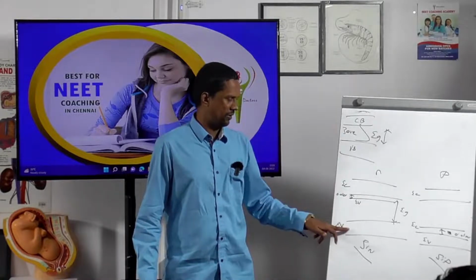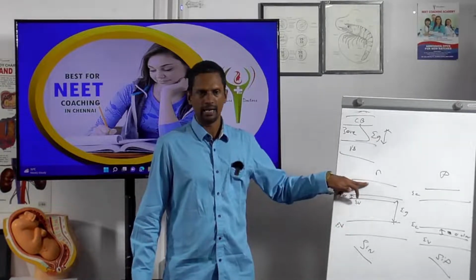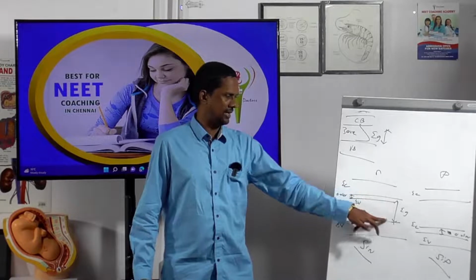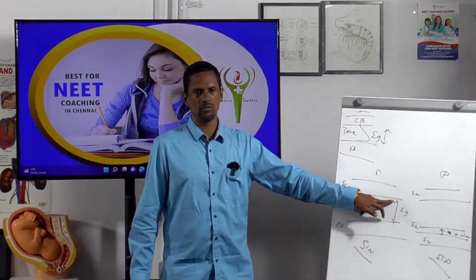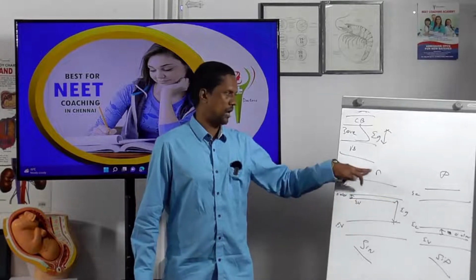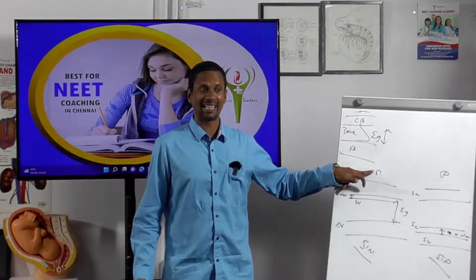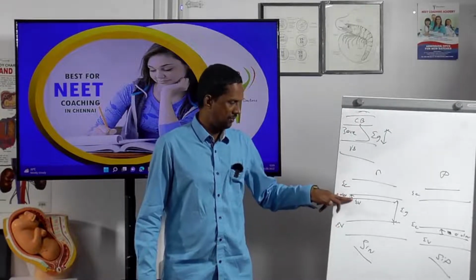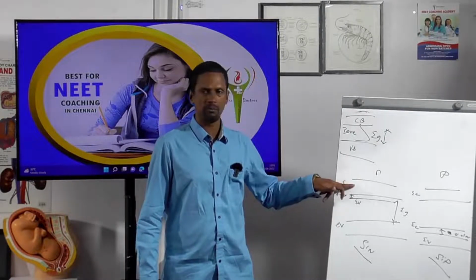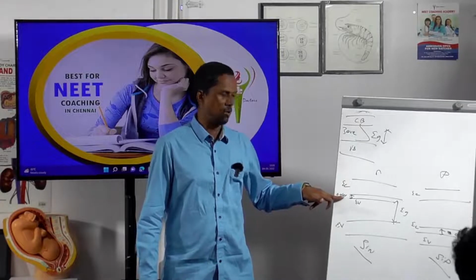Now, you know very well, valence band and conduction band. I want to show that the energy gap will fall into this range. Now it should have the n-type. N-type means it should have the excess electron. So what I can do is I can shift the valence band towards the conduction band with an energy gap of 0.01 electron volt.